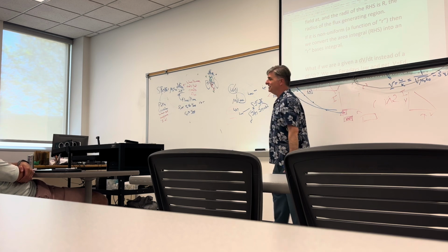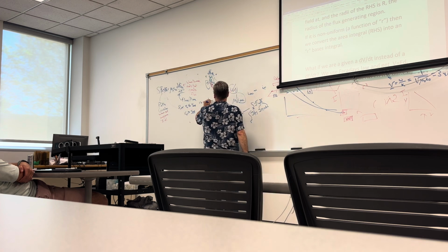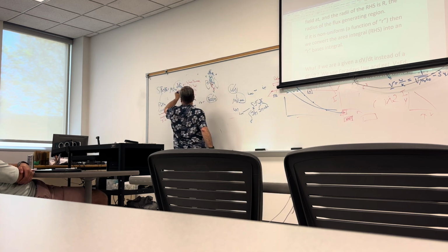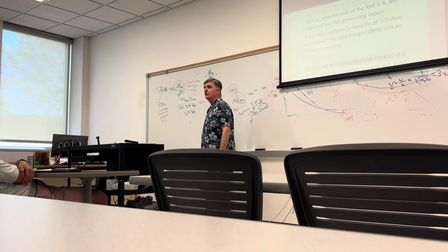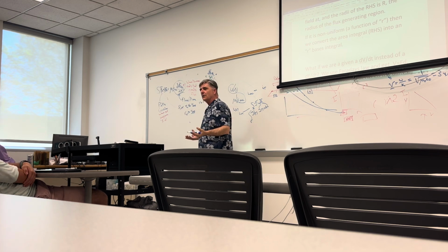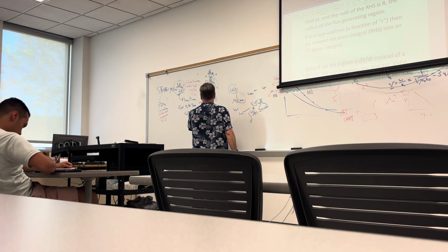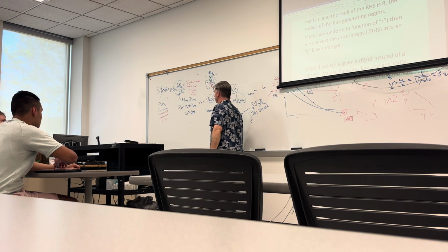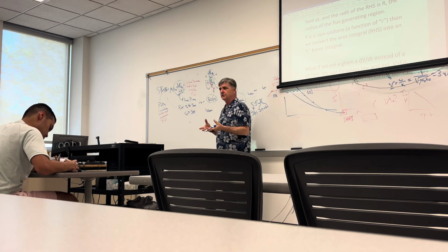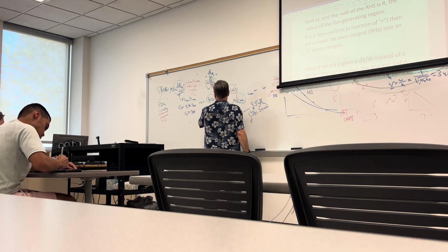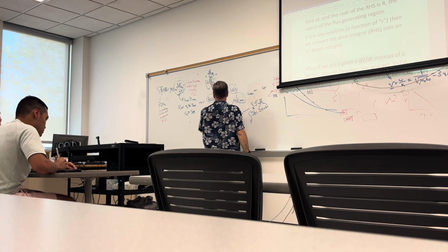So what's going to happen here? If E is not a function of R, then this term, which is the displacement current, will be a constant or a ratio of how much of it we actually have. So the I_D enclosed, they don't write it that way, but I like to remind people of that. I_D enclosed, which is just like I enclosed, is some function of the total I sub d.